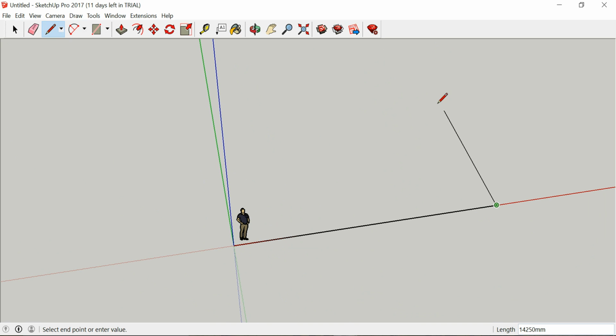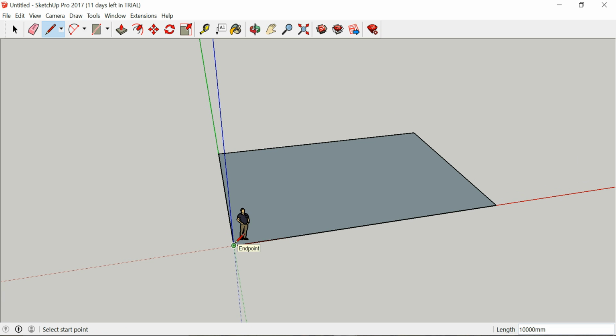If I go back in the other direction and over this way, there's it snapping to green, so we know we're going on that correct axis. If we go up here, we don't really know what axis it's going to be going in. It could be showing the green along with a little bit of height as well. So you've got to make sure you're running on those correct axes. And we know the depth needs to be 10,000. And snap that. And I'll just draw a line back to a starting point, and you can see it's going to snap there because we know it needs to be that. If I enclose it, it's then going to fill it in.